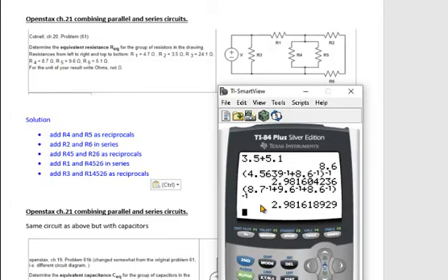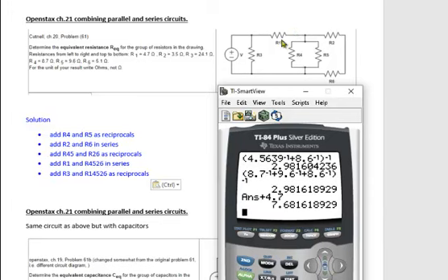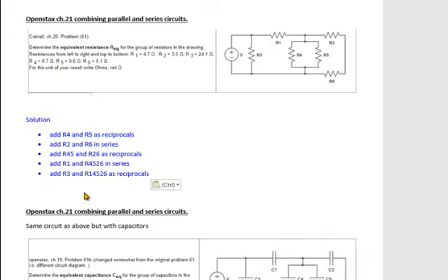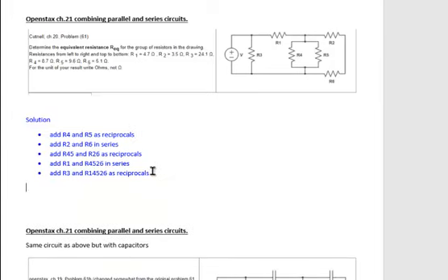Okay. Now that whole thing on the right-hand side is in series with the R1. So I'm going to add 4.7. That's what it says in the problem. Enter. And now all of this stuff over here is in parallel with the R3. So, parentheses, the answer, the 7.68, reciprocal, plus, and what was R3? 3.5. There we go. And take the reciprocal again and enter. So 2.40 is the answer. That is the equivalent resistance. So R equivalent equals 2.40 ohms. I'm going to fix that later here.